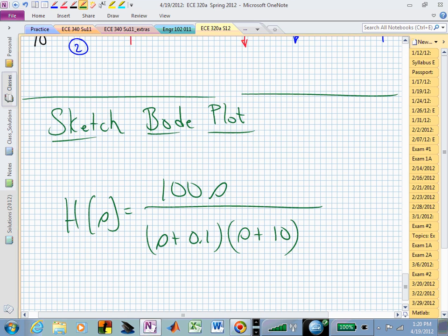And we'll scale this by minus 20 dB, the time allotment. I said 75 minutes before. A minus 20 dB reduction or change will now be a tenth of that, so you now have 7.5 minutes. See how you can use all this stuff? Oh, that's just 3 dB, up or down. And that's your half power frequency. I'll be quiet so you can concentrate.